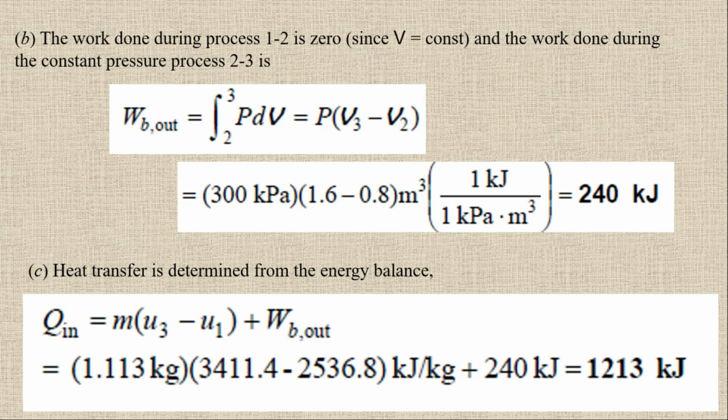So in this way we can solve closed systems. If we have a closed system and you have to find either Q or W, it always starts from the energy equation, which is E in minus E out equal to delta E system. Then check what you can neglect. If there is any value that you can neglect, simply neglect it. Write the equation, arrange the equation, and check what you can find from different sources, either from steam tables or from the ideal gas equation. And then in this way you can easily solve these types of questions.